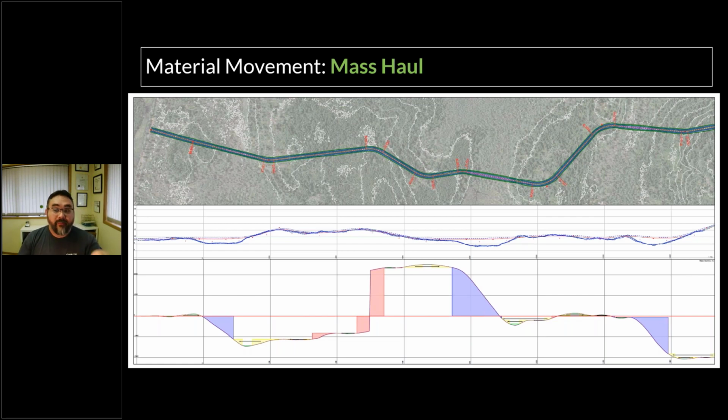When it curves above the line, as you can see from the arrows, they are pointing forward along the road. That means as you're generating that cut above the zero line, that material is required further on the road where it's dropping again. So having an understanding of that and whether you can do that or not is super important.